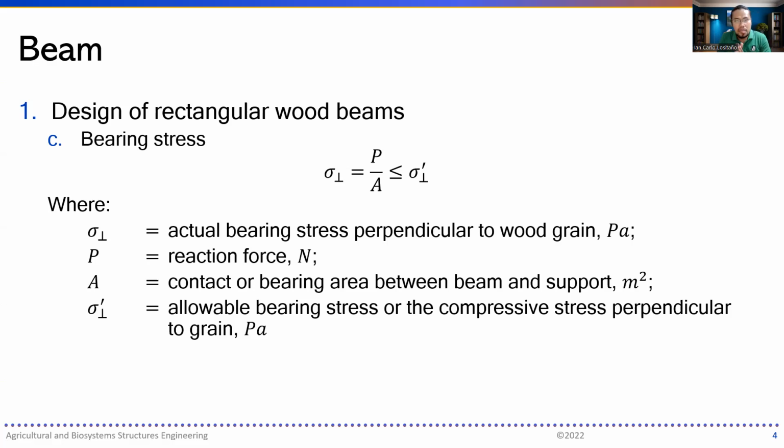Now, the wood beams are usually purchased from a lumber store or a construction supply store, in their commercially available standard dimensions or specs. So it is important, once you are trying to compute for the dimensions of your beam, you have to adjust, unless you're able to trim it down to the size that you need.